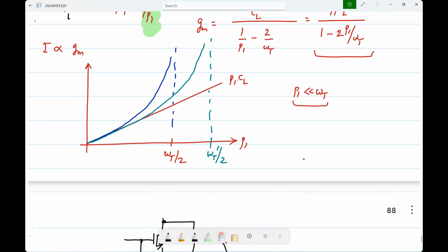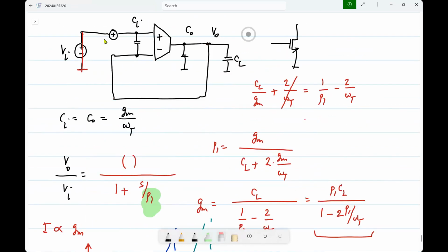So you try to go on increasing that in a given process. You will see that beyond some point, the power dissipation increases more than in proportion to clock rate, and beyond some speed, you can't realize it at all, in a given process. So there, what you do is you have many parallel paths, each one of which is operating at a lower rate. So this is some general things about technology. This was also the motivation behind asking this question.